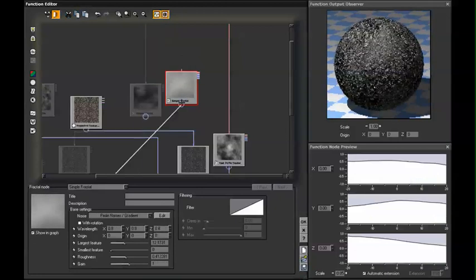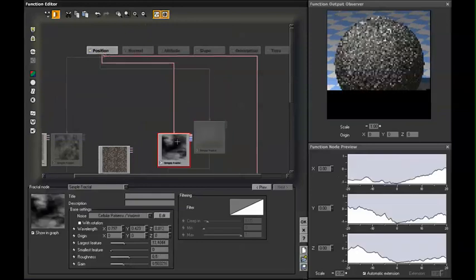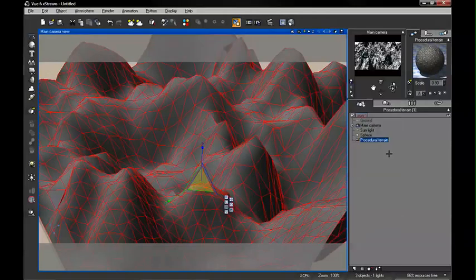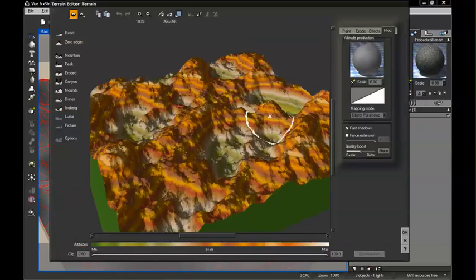And then we're going to reconnect to the pasted in fractal. It looks like I'm going to have to just take this connection, go to our position, delete that. Now the only problem with this is that we have a different scale set up for our terrain than we do for our material. So it might not show up correctly, and you might need to just change the overall size. That can sometimes vary because the scale of our current terrain is 0.9 for the material, but the scale in the function editor for our terrain, or in the terrain editor, is 0.1.